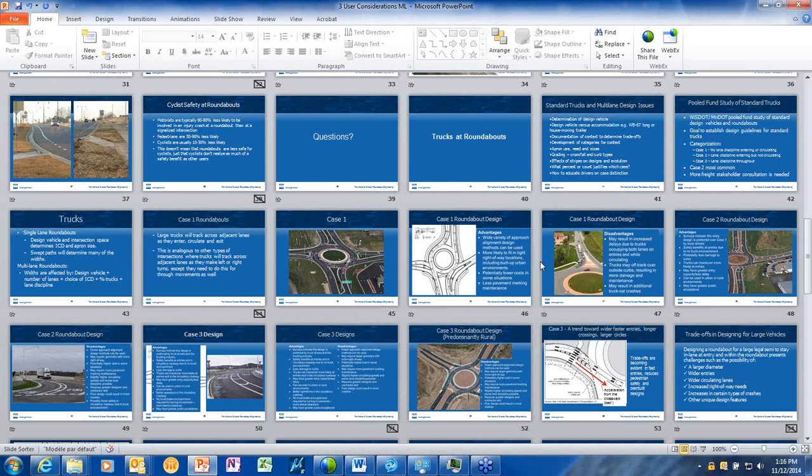Because the safety record for roundabouts overall, in the early years at least, showed a lot of promise for total crash reduction in the range of 40%. But these days, and I don't know if it's attributable to this design or education, we seem to be getting higher incidence of multi-lane crashes, and maybe the size of circles and the speed of entering traffic owing to truck considerations is one of the reasons it's happening. So I'm curious to hear what others are finding.